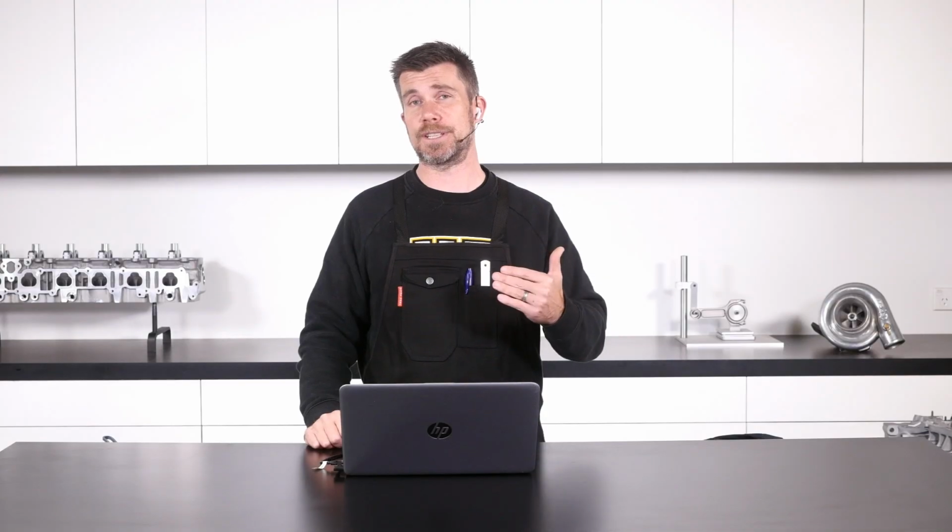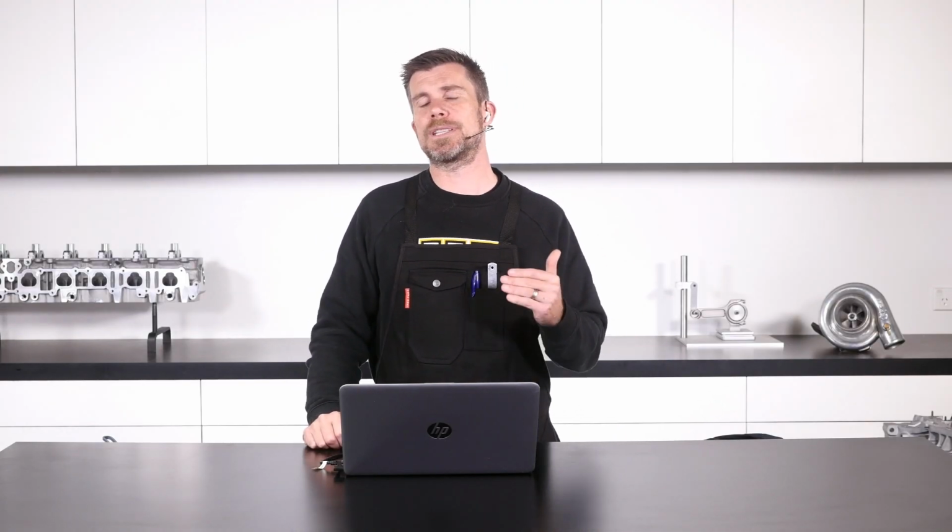So once we've done that at 12 psi and we start increasing the boost pressure, if everything's working properly, then the air fuel ratio should simply track the new target as the RPM and boost pressure increase from our air fuel ratio target table. That'll work up to a point, but once we start pushing the turbochargers really hard, let's say we get them up to maybe 18 or 20 psi, you're going to find that at higher RPM, because of the climbing exhaust back pressure, the turbos start to choke the engine, and the air fuel ratio no longer tracks your target. In fact, what it's going to do is go pig rich.